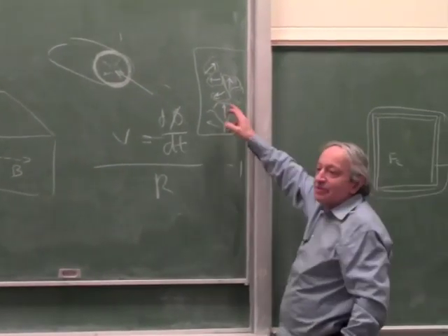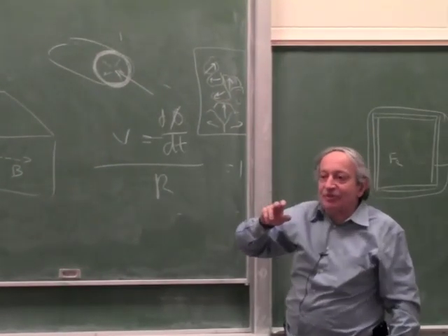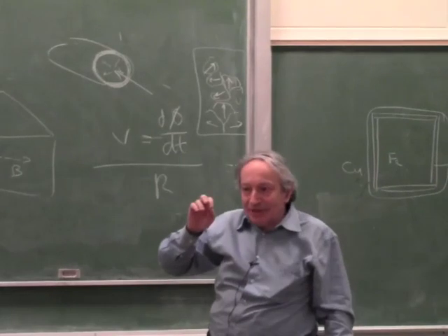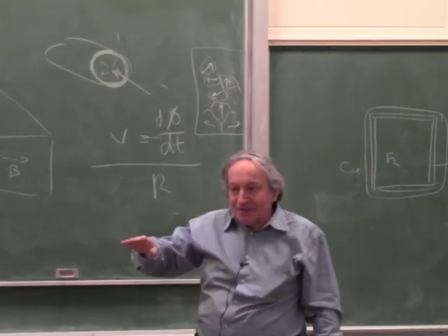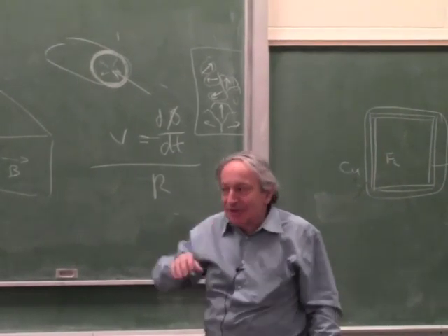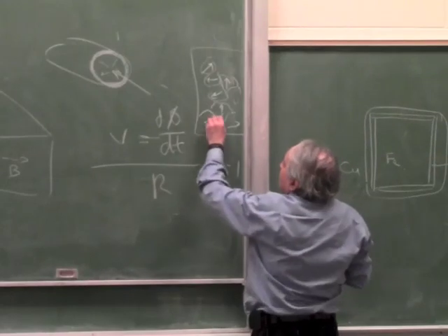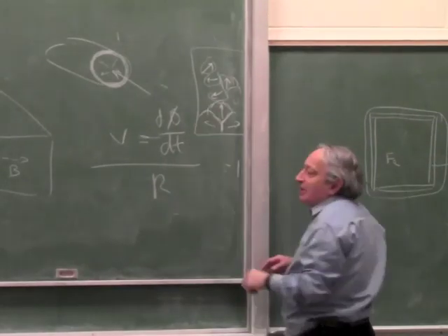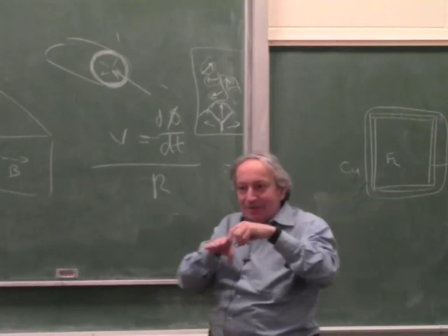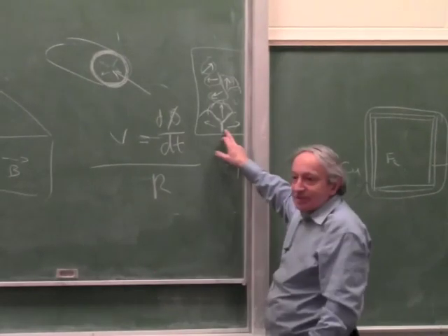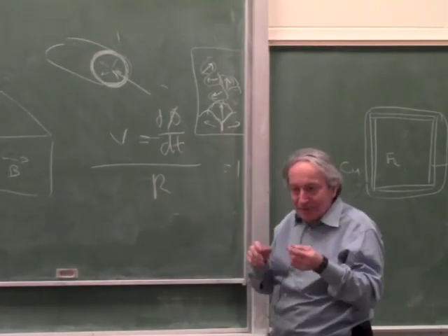These boundaries are visible. For example, if you take very fine iron powder and sprinkle it on this and look under a microscope, you can actually see the boundary, because the same way iron powder lines up between two magnets, it lines up on the domain boundary. So these are actually visible to the eye through a microscope.